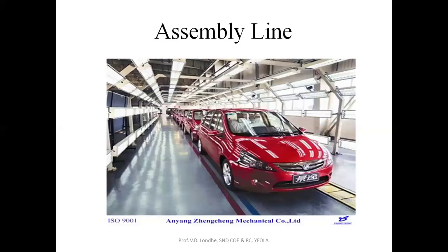Here you have to measure the percentage of carbon monoxide, nitrogen oxides, and other hazardous gases present in the emission. If they are not under control, then the engine is replaced by another engine. So these are the processes taking place in the assembly line. In the assembly line also, in the check-in and check-out, you can set the caster angle of the vehicle wheel, and the wheel alignment is also done on this assembly line. So all these processes take place on this assembly line.